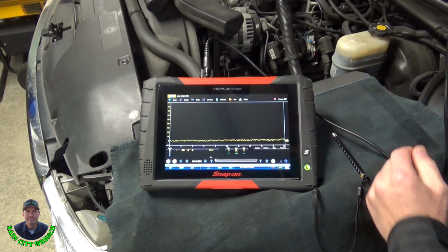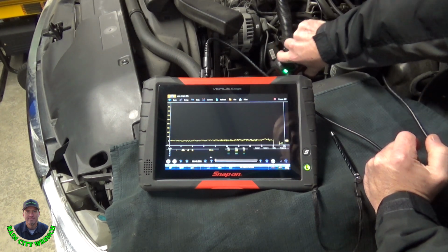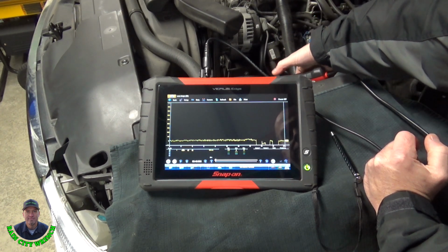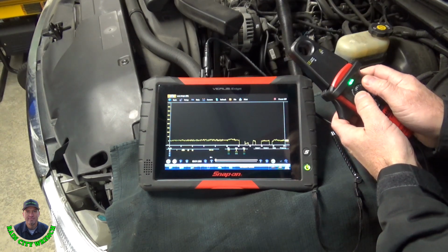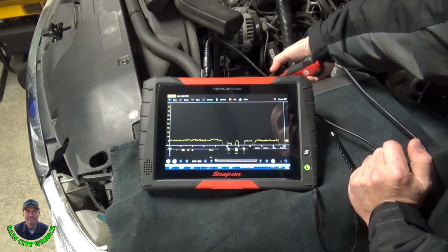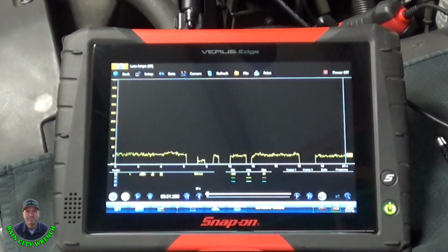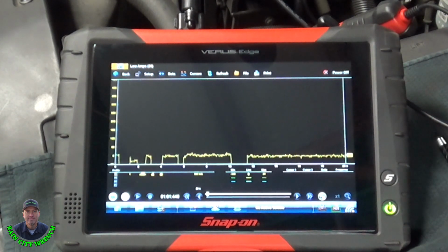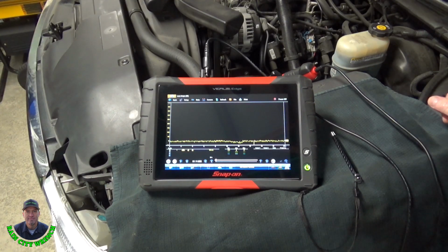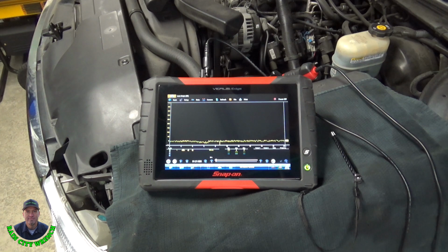So let's connect this to the negative battery cable. Whoops, reverse it. Let's double check this one last time. Yeah, pretty close. And we have nothing, which we shouldn't. I've let this thing sit for about an hour. Everything looks like it's timed out. What I'm going to do is introduce a current draw. I'm going to open up my little vanity mirror, see what that pulls.